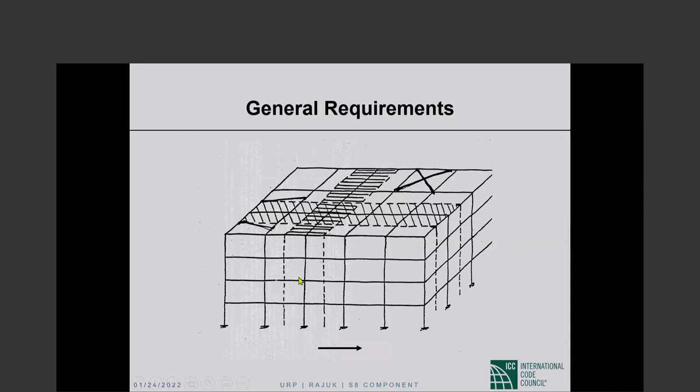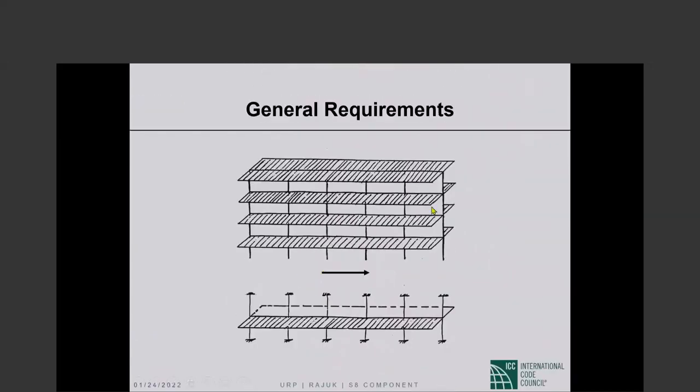Now, when you take a chunk like that out of your building, this is what you end up with: a set of columns supporting the strips of slab, and the strips of slab run between panel center lines. Okay. Now, when we are considering lateral loads due to wind or earthquakes, this is our subsystem below which we cannot go. We have to analyze this thing, and we do.